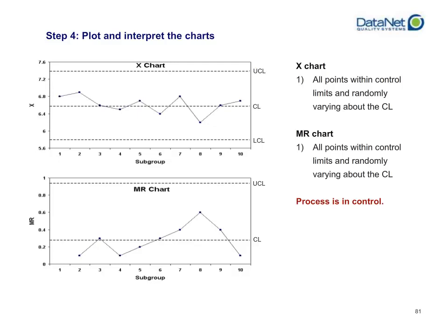So this is an example of where you really want to exercise discipline in not tampering with your process and allowing for natural variation, not trying to control your process when it doesn't need to be, when there's no assignable cause in play. You would have made things worse likely if you had tried to adjust somewhere around subgroup number 8. You would probably have caused your values to actually fall below your lower control limit, and maybe even below your spec if you were not being careful. So letting your process do what it needs to do, that is the major advantage of SPC. Not just showing you when things might start going wrong, but also to show you when things are actually behaving as they should be, or at least as they are expected to.